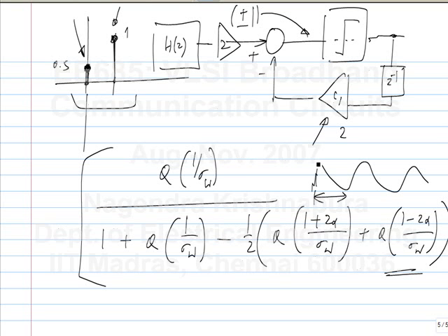So in case of digital adaptation engine, at least there won't be any implementation error. In case of analog stuff, there is even an implementation error. You think you are implementing 0.05 and it can be slightly off. In case of digital, at least that error is not there, so you can implement smaller coefficients. But it generally doesn't pay to implement coefficients like 0.001 and so on. It simply adds more hardware without doing anything to bit error rate.